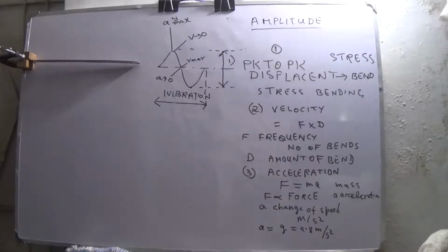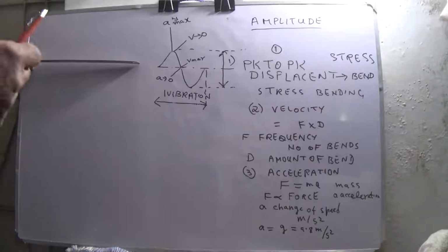For example, if there is an unbalance, then the frequency will be equal to 1 time RPM. And if the fault is misalignment, then you will see 3 vibration frequencies: 1 time RPM, 2 time RPM, and 3 time RPM. So by knowing the frequency, we can find out what the fault in the machine is. But we should know what parts are inside the machine and which frequencies they can produce in case they are faulty.